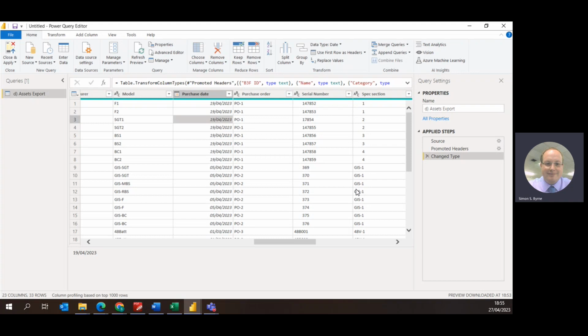One thing to note when you are bringing information from BIM 360 into Power BI through the CSV, it outputs the information in the American date format. So it would be the year, month, and then the day. That is different to the UK convention of the dates. So you may need to change that information around to ensure it changes for the UK date, especially if you are opening it up in Excel, and your Excel is configured to the UK date, and then you swap it over.